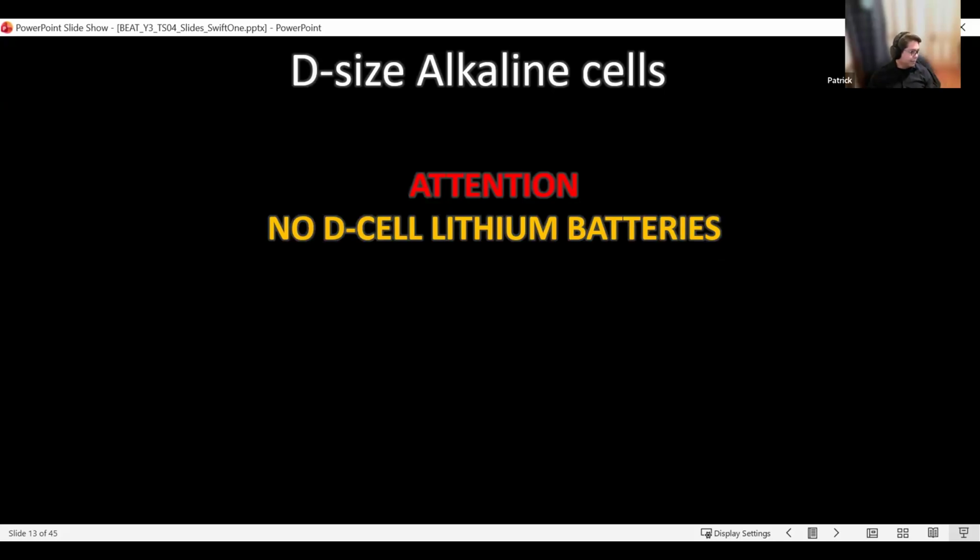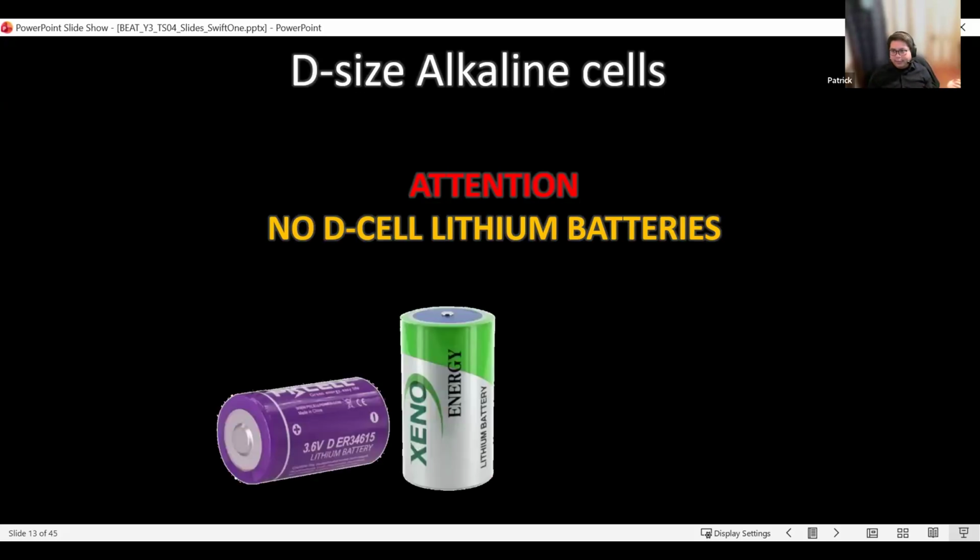And I talked about lithium earlier. In SwiftOne, lithium is okay to use if you have correct hardware to handle lithium. The issue with lithium is it's a very high energy storage. It has energy density far exceeding what alkaline battery has. That's why you can pack so much energy in such a small package. But due to that high capacity, it's also quite explosive, literally explosive. So things like this, you can buy a lithium D cell. We don't recommend using it.